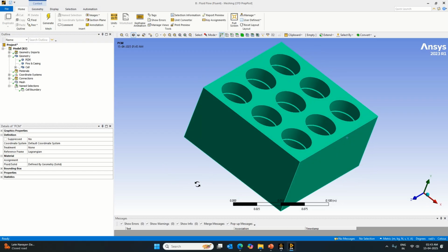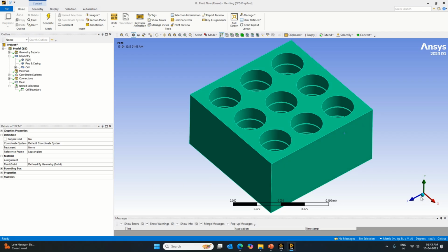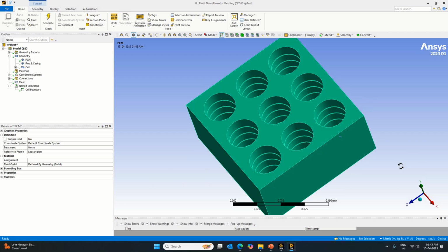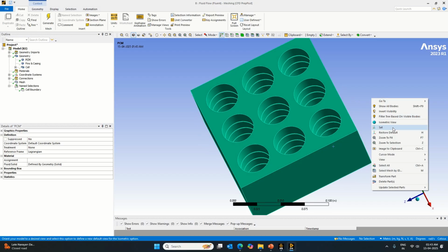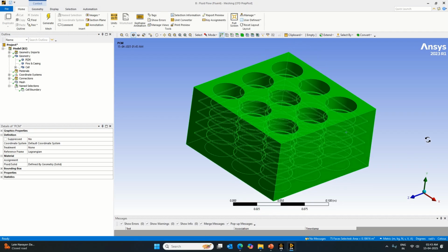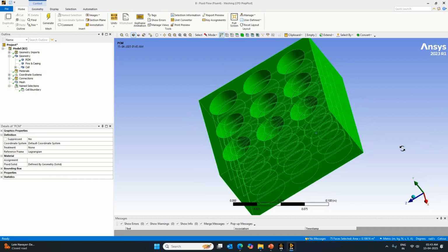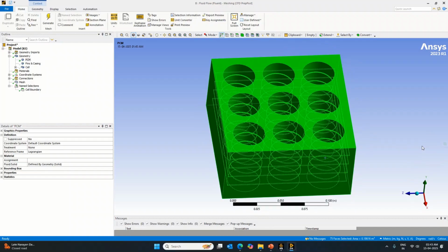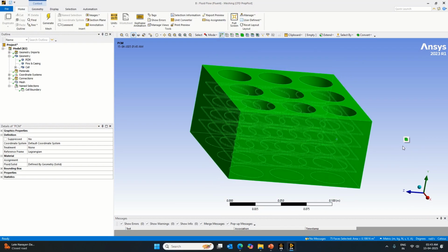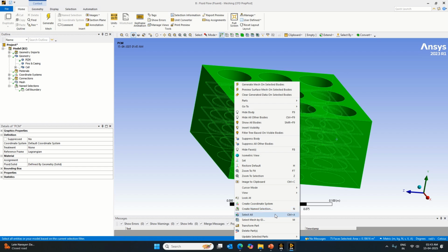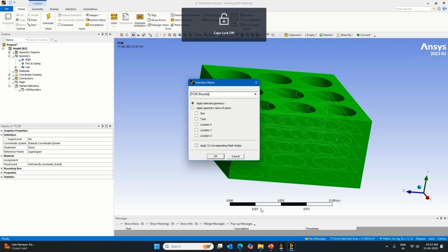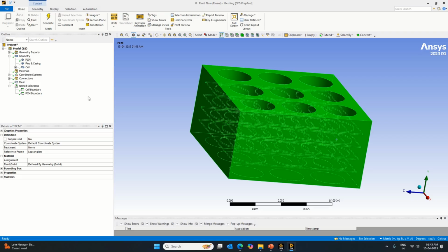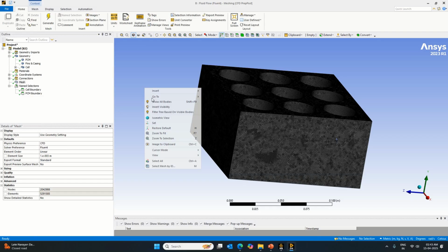So this is for your PCM boundary. For selection point of view, it may be useful later on. If you are selecting that, that is also one of the good options to go for. But you need to select all the parameters which are available, and then you can make it the PCM boundary as well. So this might be useful for us in the later stages if we are defining it. So let's select and define this. Create name selection, then I put this as PCM boundary. So I specified cell boundary, I specified PCM boundary, and let's make it show all bodies.